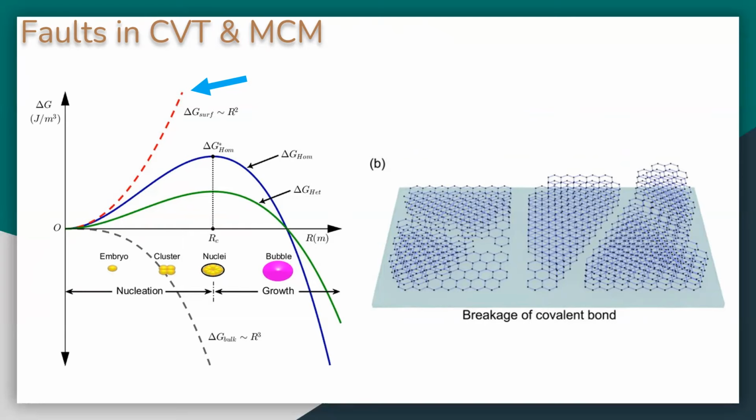And then the mechanical cleavage method using scotch tape also has some difficulties and limitations. There is no particular execution of this technique that will guarantee a specific desired amount of layers, especially when trying to extract the monolayer. This presents a low yielding issue. Another issue is that when depositing onto a substrate during transfer, there is a waste of material, since some of the flakes are still attached to the scotch tape, which will later be discarded anyway.